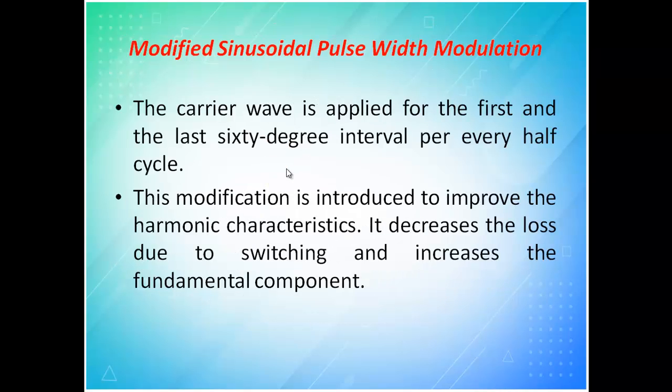Now even from Sine PWM we are able to go for a modified Sine PWM technique. In this modified Sine PWM technique, we will slightly change what we have done for Sine PWM. So gradually we will increase, and the center portion width will be more. That is called modified Sine PWM.